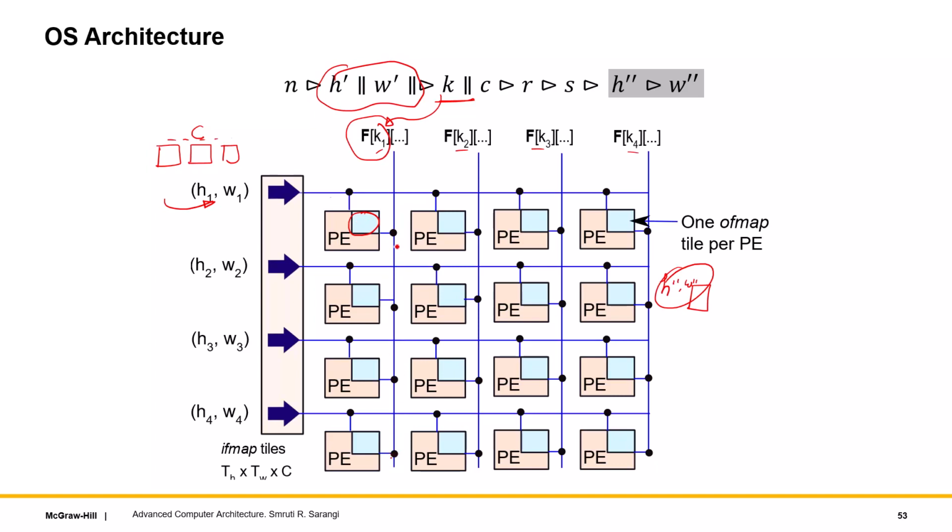In this case, there is no great systolic transfer, because the partially computed output stays here, the input gets streamed, the filters get streamed, then they collide here, the output is computed, and they don't remain here but get streamed through the bottom and written to memory. I deliberately went slightly fast because I'm assuming that you have understood the previous few slides.